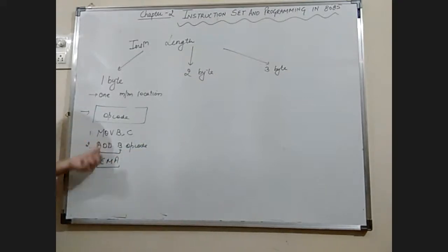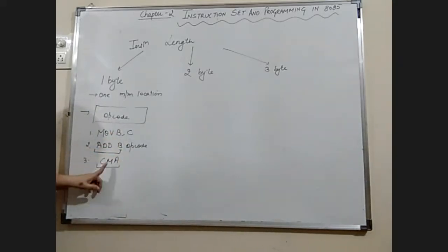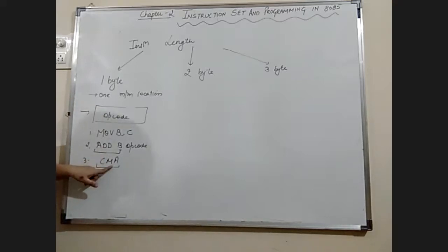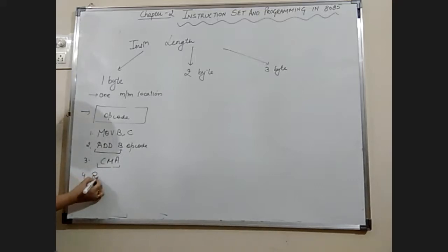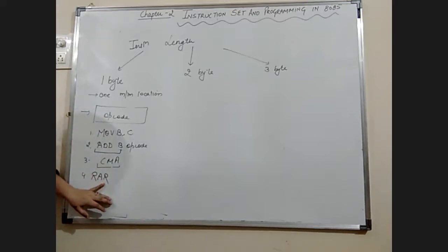Okay. So likewise, in this instruction, the data is present in this register only, and here the data is present in the accumulator, which we have to complement. Okay, the next instruction we have is RAR. So that means rotate the contents of the accumulator right through the carry.